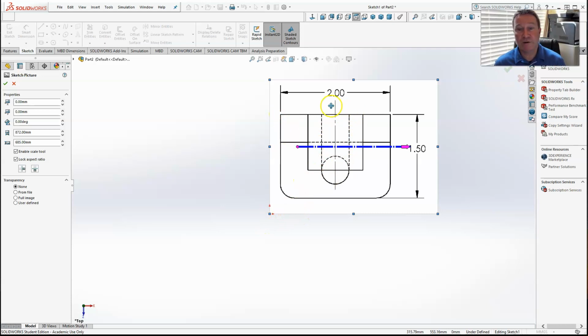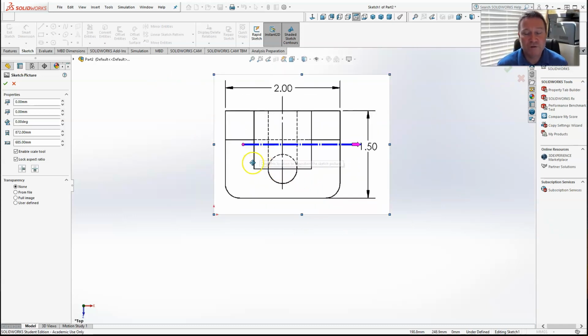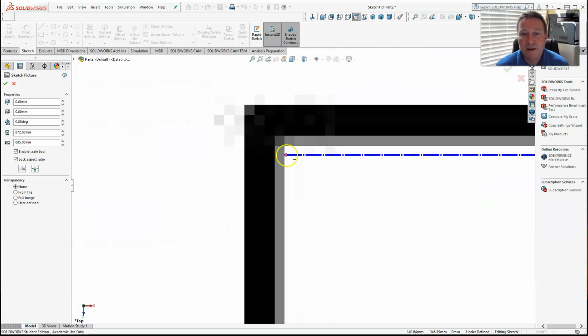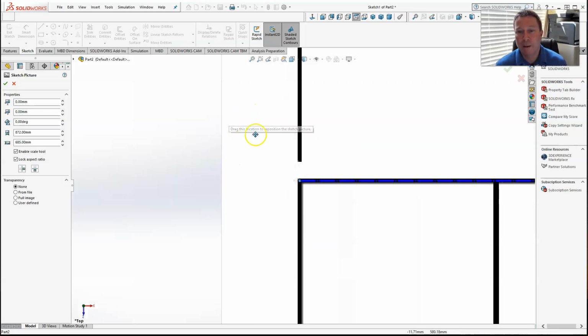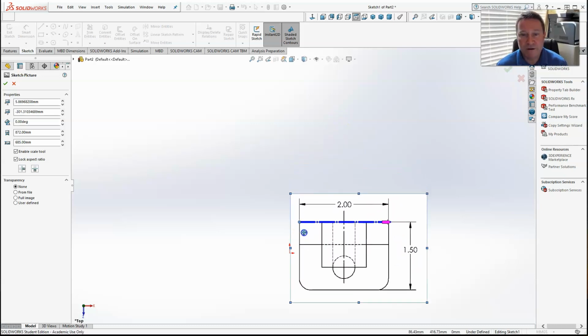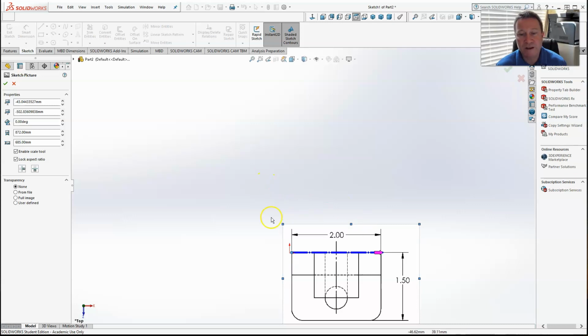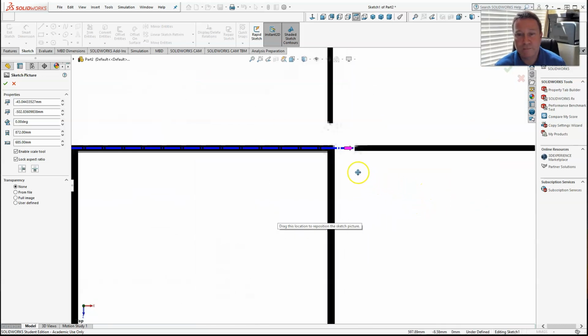Now sometimes the problem with that, if I were to scale this picture where it's currently located, it will end up maybe somewhere over here, and then I'll have to search around for the part origin. So one little trick tip I found, same thing as we did last time. Let's find our central portion. 1, 2, 3. I'm going to guess right in this colored block right here. I'm right down the vertical and the horizontal, right down the center. Before I actually scale the picture, I'm going to move the entire picture closer to the origin. That way, when it scales down, it'll be close to this area. Then we'll have to look for the origin.